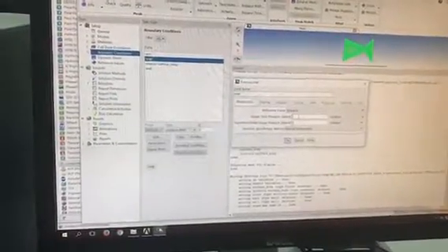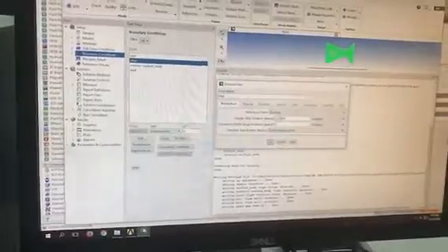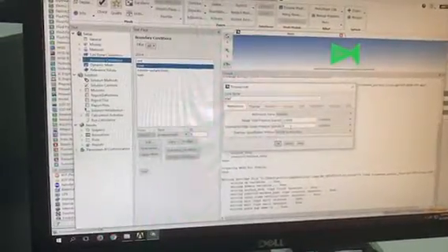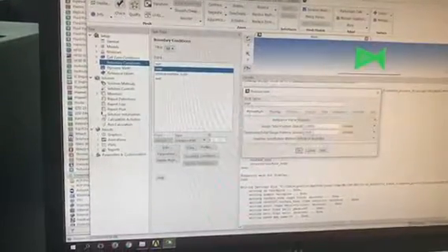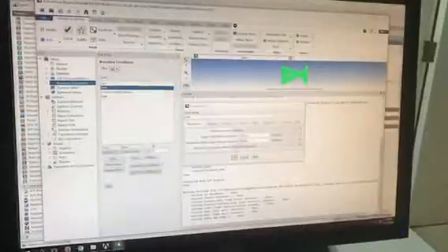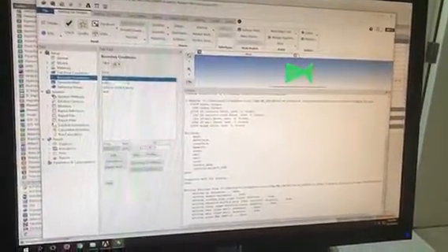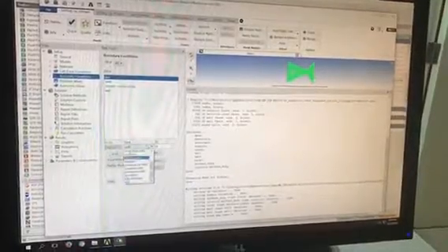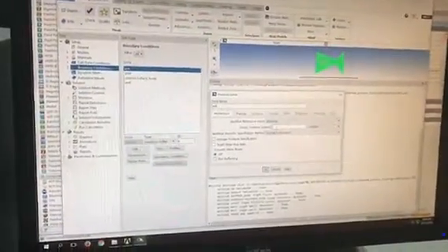We're going to go for 1,100,000 for this case. Supersonic pressure to be 100,000. We press OK. We go to the exit. Change it to pressure outlet. And the gauge pressure, we want to change it to 4,000.